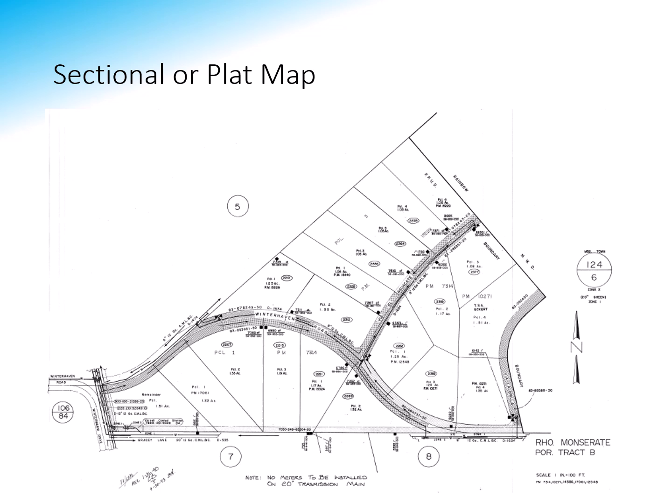So if you have a main break, you're going to be able to see who's affected and how to shut it down. The only thing lacking on this would be longitudinal lines, so you would know which way it's flowing. Is it uphill, downhill? Because that can impact how you're going to drain it or fill it.